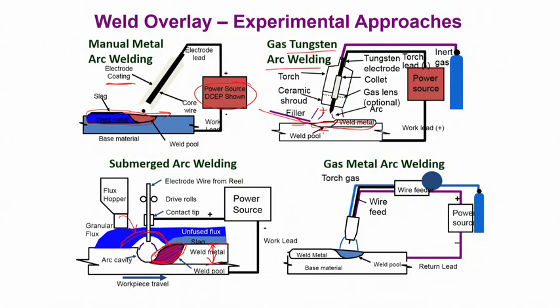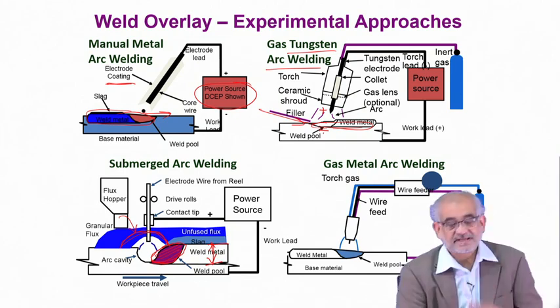The slag phase is molten, but you also have a solid crust on top of that. That means it is completely covering and protecting against possibilities of external oxidation, and the weld pool can be fairly deep, but most importantly doesn't come in direct contact with air. So you have a much cleaner weld overlay with very little scope of trapping any bubble, porosity, or even slag particles.